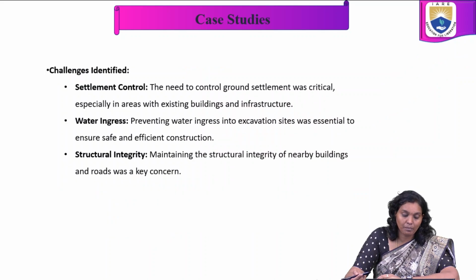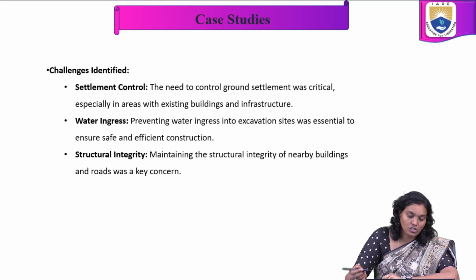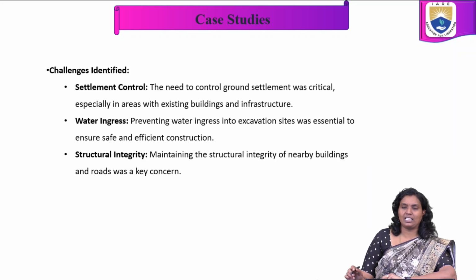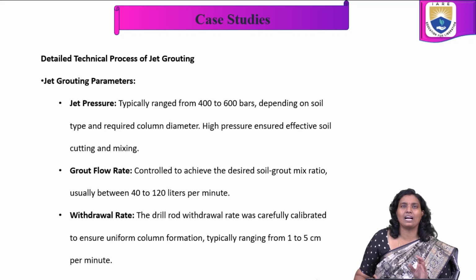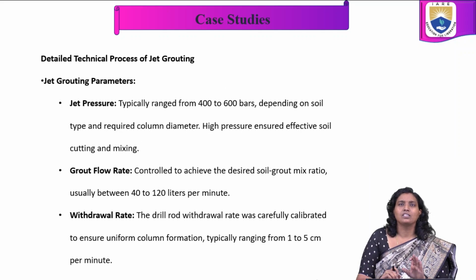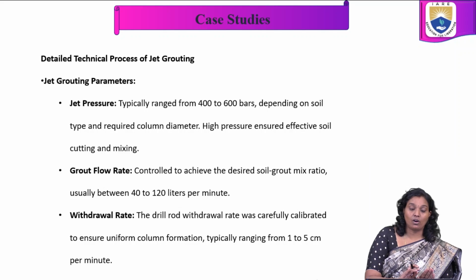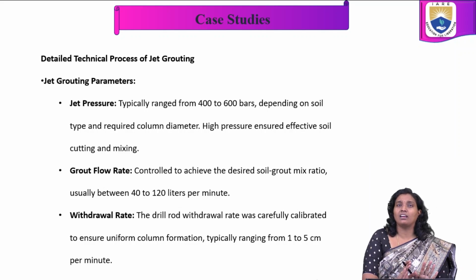In settlement control, the need to control ground settlement was critical, especially in areas with existing buildings and infrastructure. And also water ingress: preventing water ingress into the excavation site was essential to ensure safe and efficient construction. In structural integrity, maintaining the structural integrity of the nearby buildings and roads was a key concern. These are the challenges which we identified. So in this, we decided to go with jet grouting.